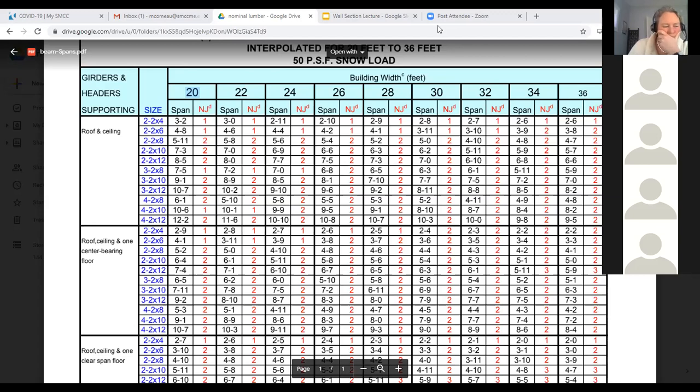We talked about it because the engineered wood would expand and contract differently than the nominal wood. Could I use a microlam beam and have it be in line with the I-joist so that the floor framing isn't so big? Absolutely. Yes, that's exactly what you would do.